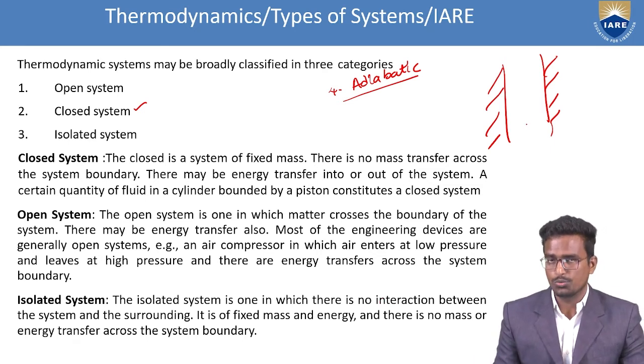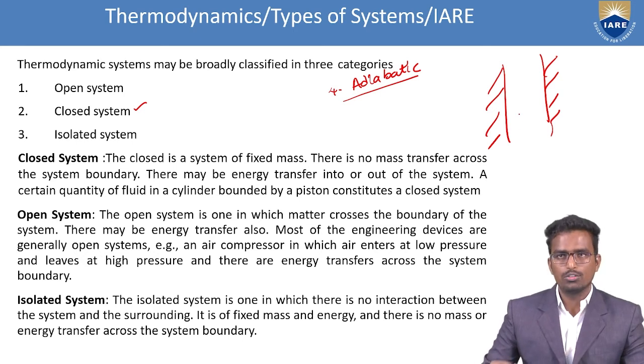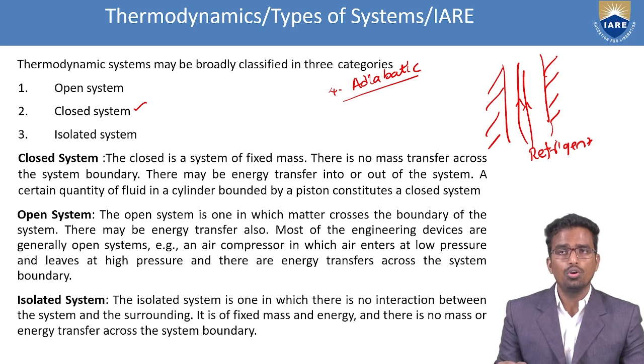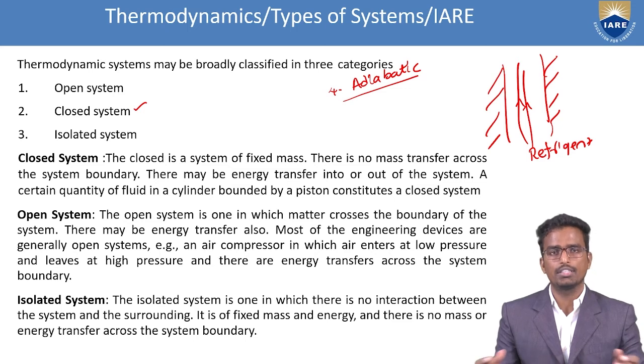The example for this is an air conditioning system, where we see the copper pipes wound with rubber tubes. Inside the copper tubes, the refrigerant is flowing. That means mostly a cold refrigerant fluid is flowing through the refrigerant pipelines. If the cold fluid is interacting with the outside world, a heat exchange will take place. That means absorption of heat takes place right there, and we are not getting any cooling effect inside.